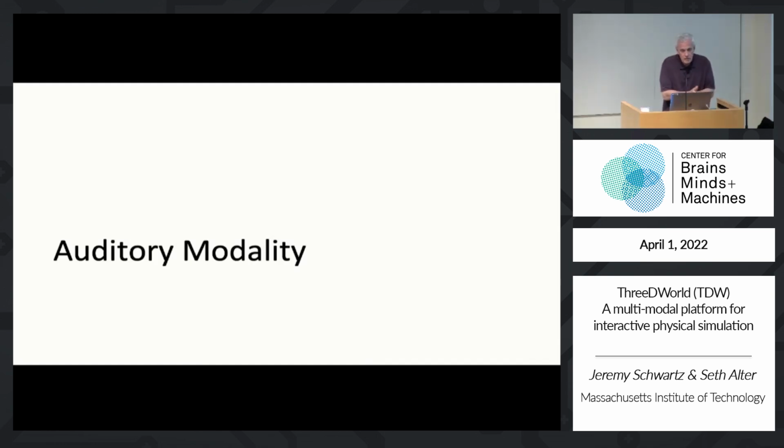Talking about audio, the audio modality is equally important in TDW, and the platform provides a high degree of acoustic rendering fidelity. For sounds placed within interior environments, TDW uses a combination of Unity's built-in audio and Resonance Audio's 3D spatialization to provide real-time audio propagation, high-quality simulated reverberation, and directional cues via head-related transfer functions. Sounds are attenuated by distance and can be occluded by objects or environment geometry. Reverberation automatically varies with the geometry of the space, the virtual materials that are applied to walls, floor, and ceiling, and the percentage of room volume occupied by solid objects such as furniture.